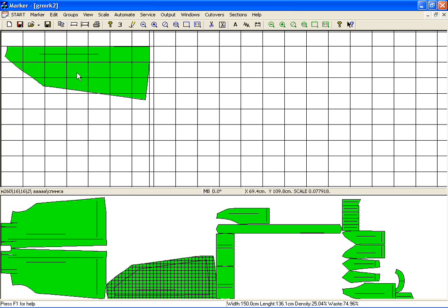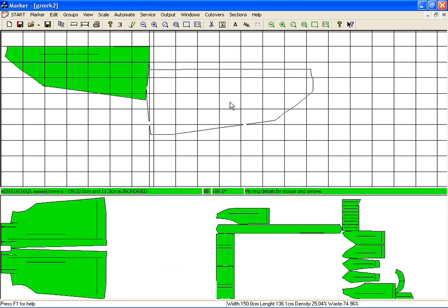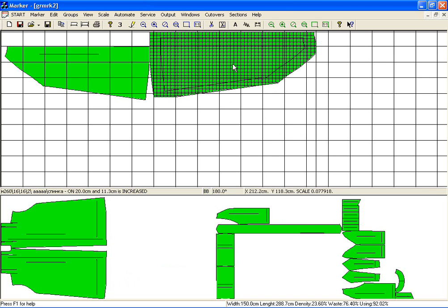Method 2. With individual adjustment. The draft is increased by certain warp and weft values. After the cutting process is over, the base draft is superimposed on the increased draft, is arranged according to the pattern lines, and the trimming operation is performed. The increased value required to align the draft patterns is calculated automatically. The pattern share value necessary for alignment is set by the designer while producing the model in subsystem pattern design and modeling.